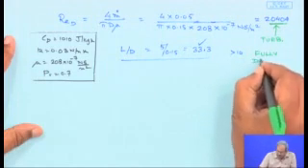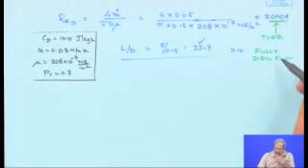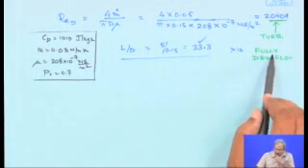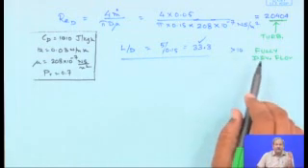So a fully developed flow relation for the case of turbulent flow may be used in order to obtain the heat transfer coefficient. We understand that in some cases the flow may not be fully developed, and therefore a significant portion of the pipe might be under developing flow. So any relation which is valid only for fully developed flow may not be used in such situations.